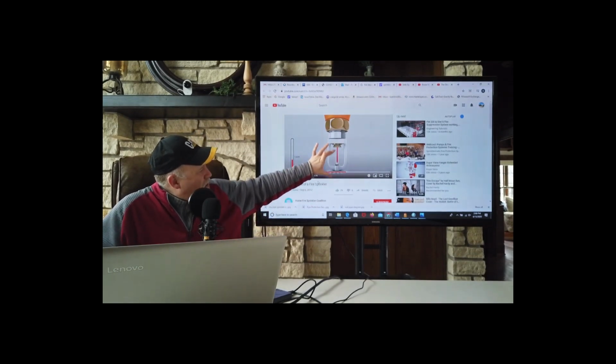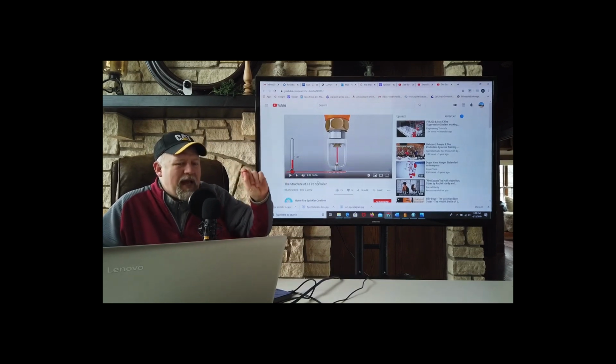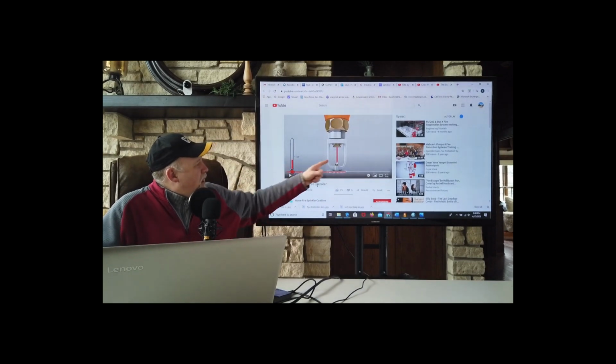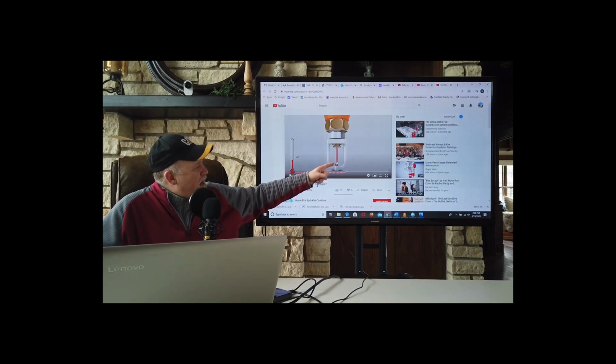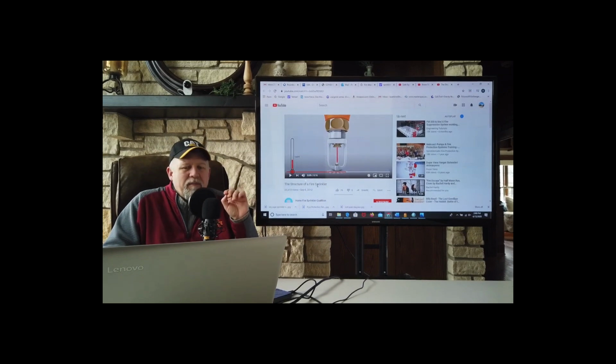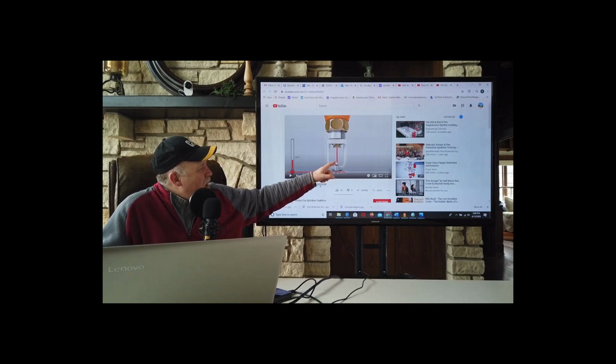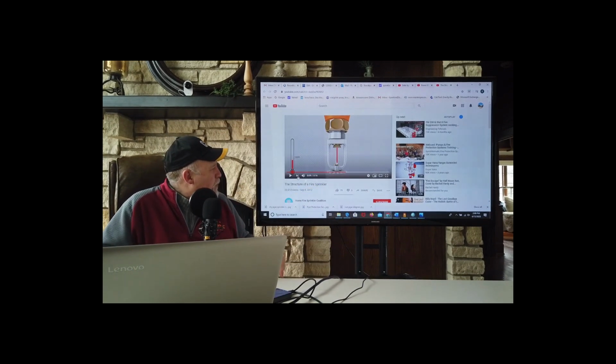This colored piece of glass has a fluid in it with a pretty high thermal expansion coefficient. There's going to be a little bitty glass bubble in here. And notice, different sprinkler heads are designed to break at different temperatures. Different colors, rather, are going to break at different temperatures. Once it reaches the appropriate temperature, in other words, that's what tells the system that we have a fire. We have achieved a temperature that shouldn't be in that space. That colored fluid breaks.